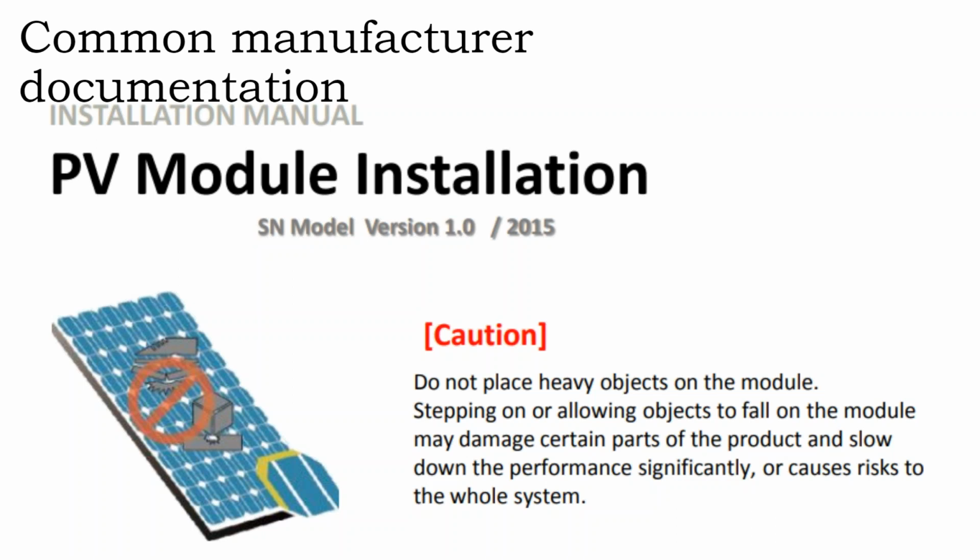So what I mean by this is you can cause little micro cracks within the solar panel itself that are not obvious and are not immediately going to cause a problem, but the electricity flowing through the panel over its life will make those micro cracks into larger canyons, almost like water carving out the Grand Canyon. Little defects in the cells can start to unzip, and you get lines and streaks going across your module cells, and sometimes that creates problems, sometimes it doesn't. There's a degree of inevitability in module failure.